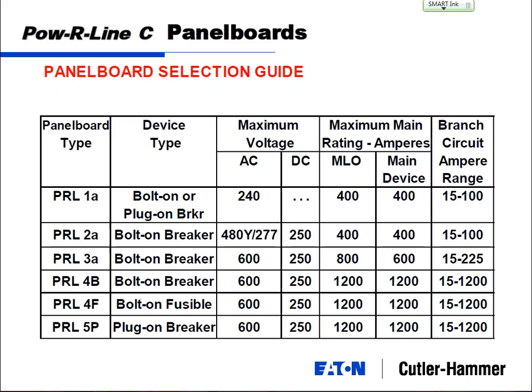Jump back to one of my earlier slides. I said there are two kinds of faults you can have: an overload or a short circuit condition. An overload is an extended period of time where you're barely over the rating of the circuit breaker. So maybe I've got a 20 amp circuit breaker and I'm plugging a 25 amp piece of equipment into the socket. I can run that for 5 minutes, 10 minutes, maybe even 15, a half hour. You're not really sure exactly. You're going to gradually overload the circuit to where it's going to trip.